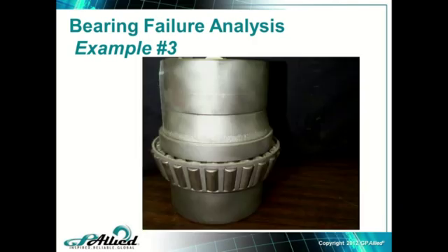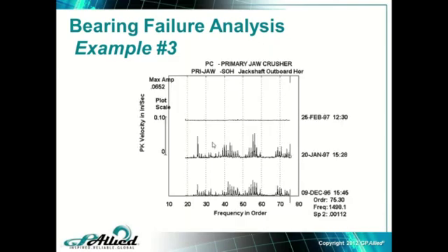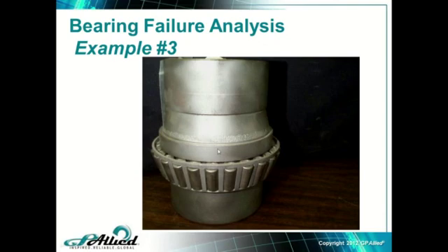Last one, for those of you sitting here looking at this thing. Now, the vibration data just shows that there's a bearing fault. Right? It was there on the first reading in December, and it wasn't much worse in January, and then, of course, sometime in January or early February, it was repaired, and you can see the bearing frequencies are there. Now, here's an example of what I'm talking about. This one had another one of these things right here. We cut one off and didn't cut the other one off.